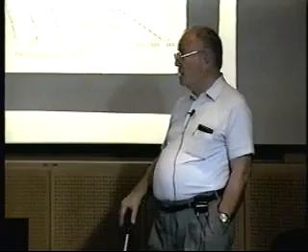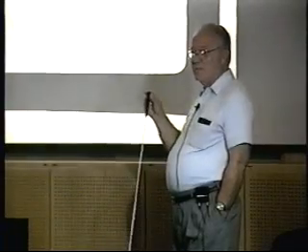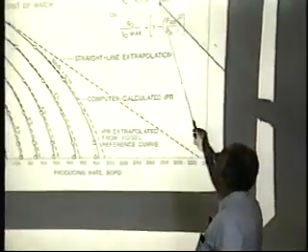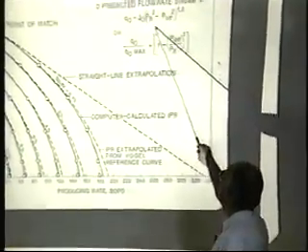So I went out and got a bunch of data, including some on Ekofisk, and sure enough, when you plot the data up, it plots as a difference in pressure squared. As a back pressure curve plot, the shut-in pressure squared minus flowing pressure squared versus Q. And it's a straight line on log-log. And this is a form of an oil well inflow performance.